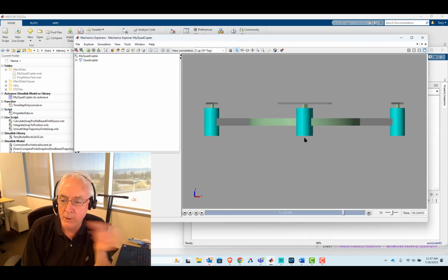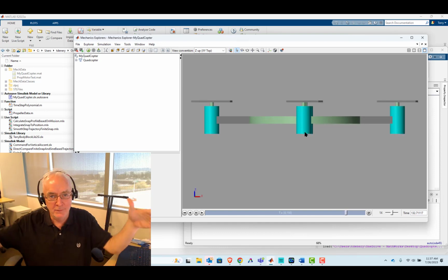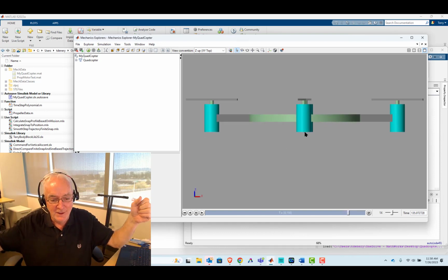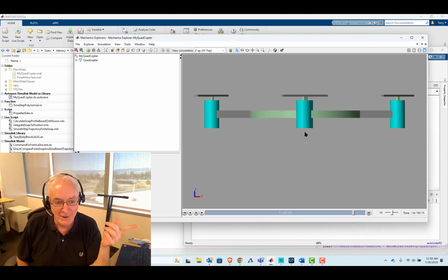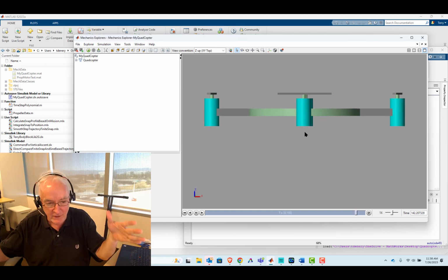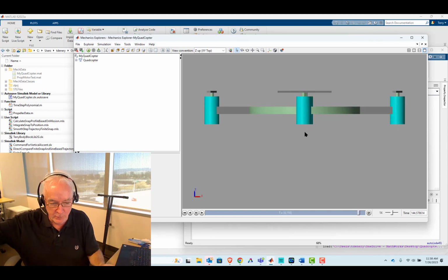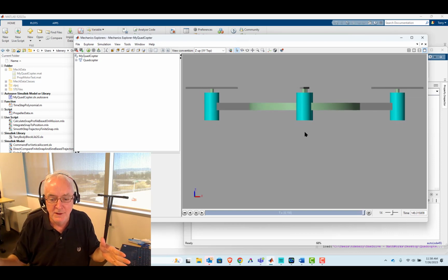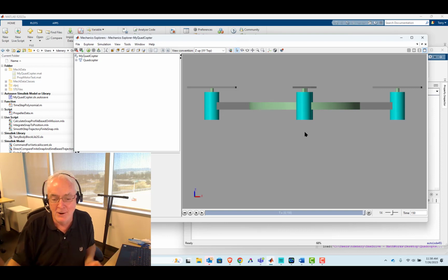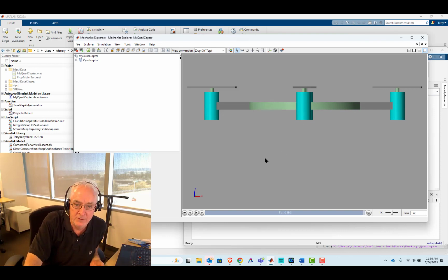All right, but what I wanted to really show is that 1,000 on thrust, which is directly the force that's generating the moment, is good for the X and Y rotations. It's nowhere near good enough to do this Z rotation. And all I'm really saying is that propellers are light and small inertia, and therefore the torque required to push off and get that rotation is a little bit harder, right?